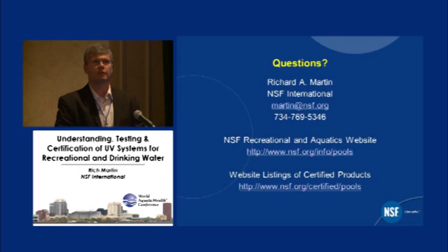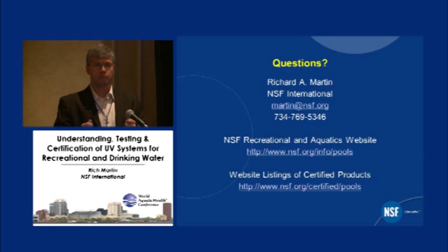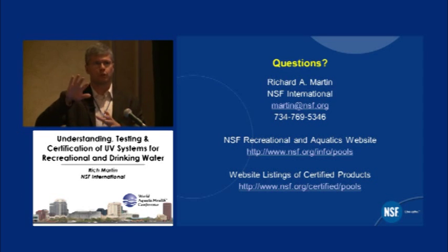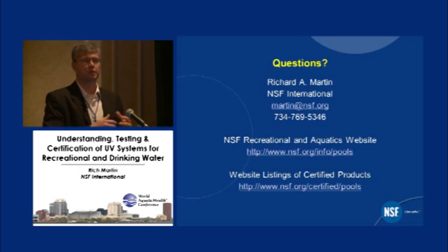Right, thank you. The question was about biofilm production and how that can make transmission of the light problematic. Basically, if you have a biofilm-coated surface, biofilms can prevent transmission. Okay, so the issue is that biofilms, which of course can cloud or occlude and prevent transmission of the light, mean you won't be able to achieve that same level of treatment and disinfection.